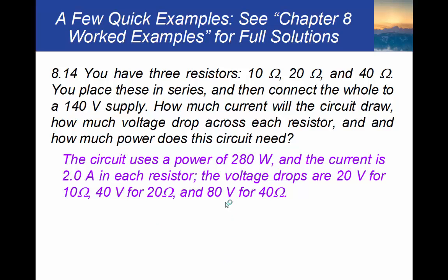Notice that if you add up 20 plus 40 plus 80, I'll let you use your calculator to double check this, but you get 140 volts, which is how much you started with. So that's a good double check to make sure that we've done everything right, or at least that we've done this part of it right.